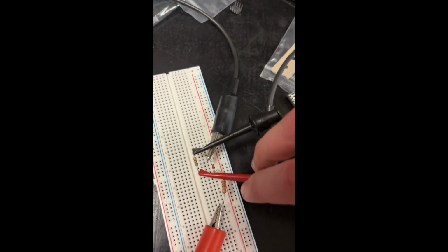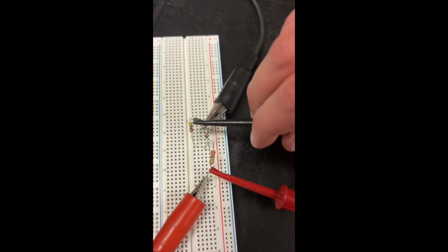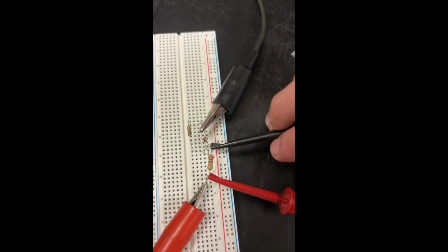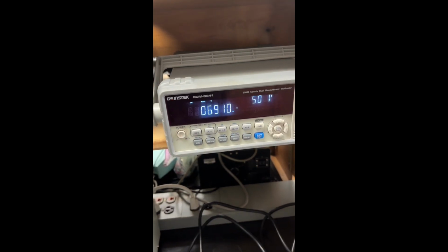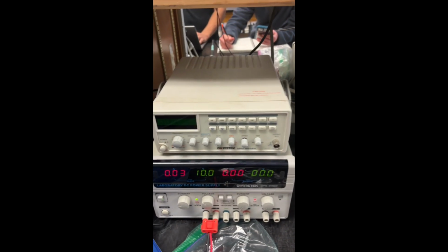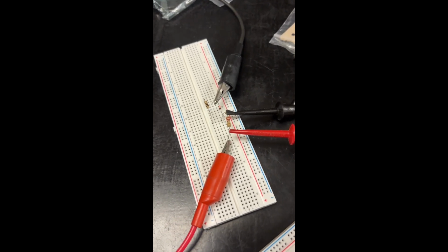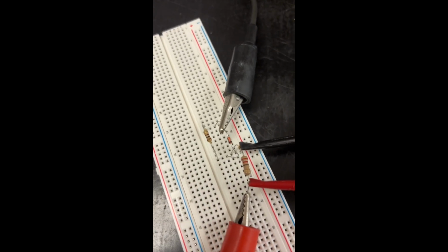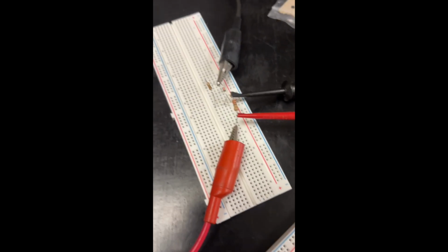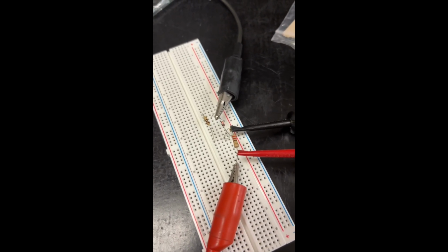And then I will measure the voltage across here, which gives us 6.91 volts. And so I can use those voltages and resistances in order to calculate the actual current flowing through, instead of measuring current in a parallel circuit there. Meaning that this will give me everything I need to calculate my final value.